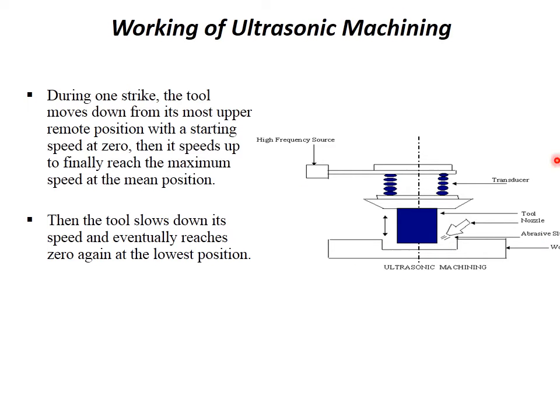In the same way, here the schematic is given. You can see the ultrasonic machining setup, where a bath is given. In the bath you can have the abrasive slurries filled continuously through a nozzle. This is a tool. The tool comes with the ultrasonic transducers, which can give you different frequencies, but it has to be more than 20,000 hertz.